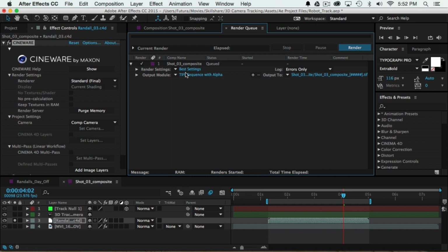So I've actually already done this, and there's no way around this but rendering stuff out of Cinema 4D or any 3D software at any decent quality is going to take a while. So for all of my shots, each frame took around 50 seconds to export, and almost every shot had about 90 frames, so 50 seconds times 90 frames is about 75 minutes, so it took an hour and 15 minutes on average to export each shot. And this is why I prefer to export an image sequence. Since the renders can take so long, you don't want to lose all of the time that you've already spent and have it crash 90% of the way through.